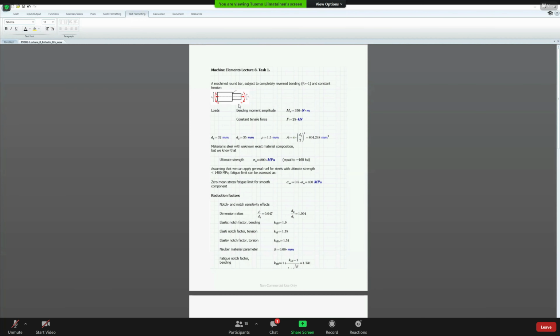In a rotating machine, it's usually the case that you have, for example, gravity load. There is some coupling or some large pulley or whatever hanging on the shaft end, and that is bending the shaft end, of course, towards the earth from the gravity. And due to the rotation, the direction of the stress in the shaft is changing, which means that at the start of the rotation, the bending is at the top and the compression at the bottom.